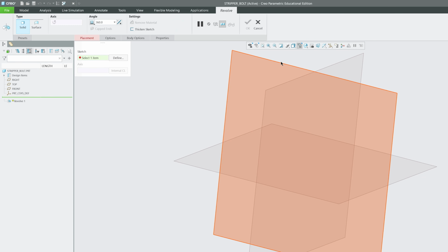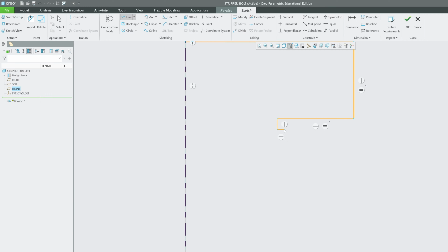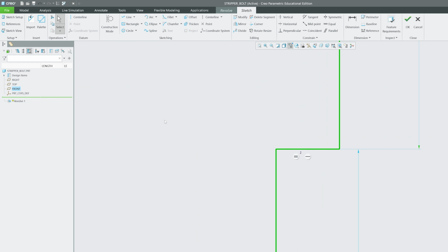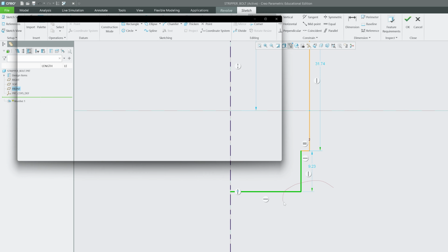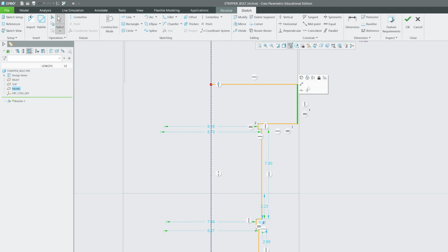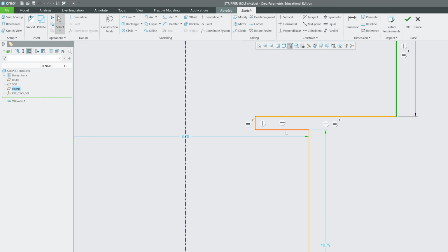and let's build this bolt real quick. Probably I'm gonna use revolve. Let's take center line. Now plot head with of course undercut, and then again I'm gonna leave some area for threads, and here also I think I should add one undercut. Okay, so let me delete these segments. All right, so let's make this how much it should be. So let's make it 15, and I'm gonna give it a height of 8, and let's also try shift this a bit, and probably I can give this a distance of, this one needs to be 0.5, and I can actually make this equal to this.